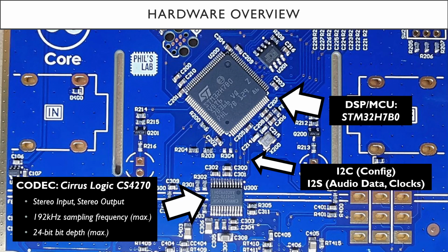I2C in this case doesn't have anything to do with the actual audio data transfer, which is achieved via additional I2S lines, so integrated sound, which is very typical for audio data and also has several clocks, and we'll go through that in a bit of detail also in this video, but again, this is predominantly focused on the I2C register config for setting up an external codec.